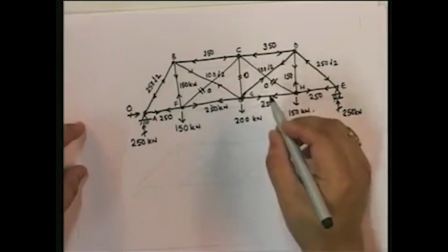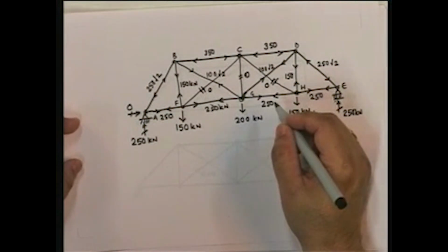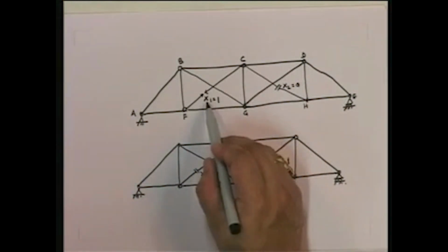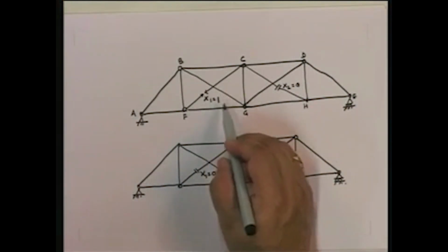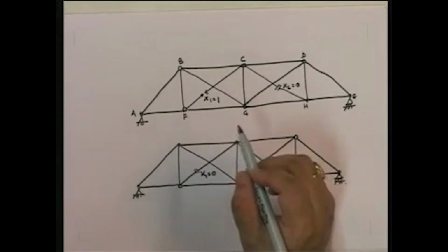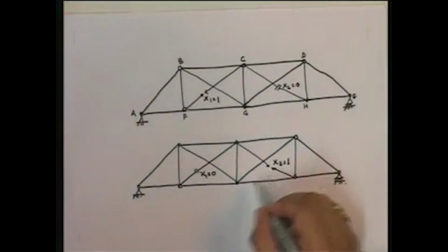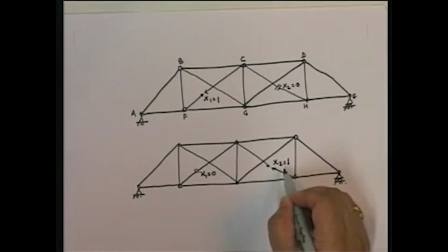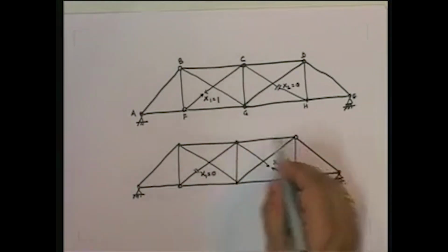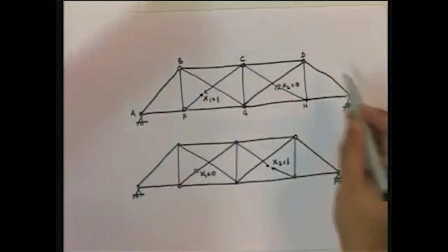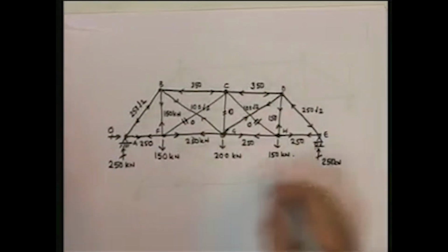Now the loading we have done. In the loading, if I need to find out this displacement, and I am using the principle of virtual displacement, what would I do? I would use a virtual force system where this was equal to some arbitrary value. I might as well take it equal to 1. Okay? Now if I wanted to find out the displacement here, what would I have to do? I would have to take a unit force corresponding to this, and then find out the work done. So this would be the virtual force system to find this displacement under this loading.